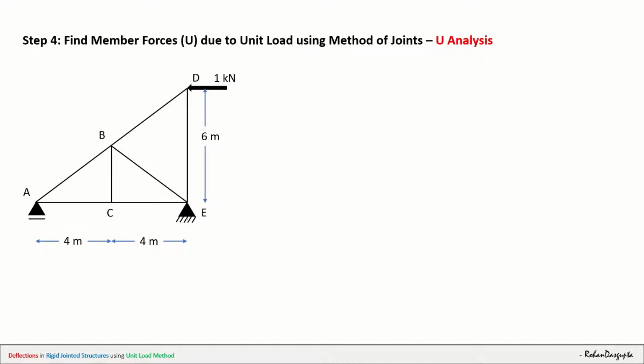So here what I will do is I will take VE in the downward direction. VE is 0.75 in the downward direction. Right. And here HA was on the right hand side, 1 kilonewton. And VA, vertical at A, was 0.75 kilonewton in the upward direction. Okay. So in that figure only you can just make this change of VE.